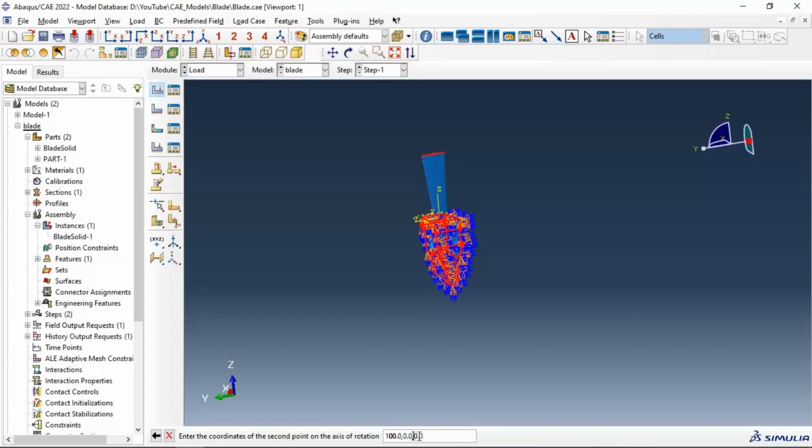And also now we have a wrong value. We have minus 250 millimeter, not 250 millimeter, because we are in the z direction. This is the inverse direction, the minus value, not the top value. Okay, let's select the second point: 100, and minus 150 millimeter. These are the coordinates of the 2 points of the axis of rotation.